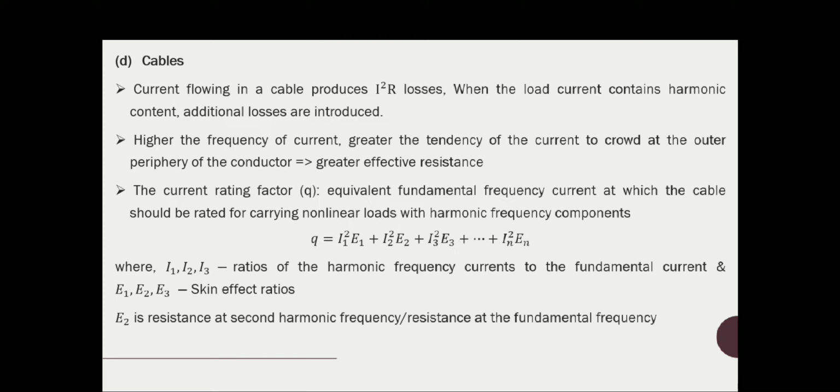And this effect of harmonics in cables can be expressed in terms of the current rating factor, which is represented as Q. The current rating factor is the equivalent fundamental frequency current at which the cable should be rated for carrying nonlinear loads containing harmonic frequency components.